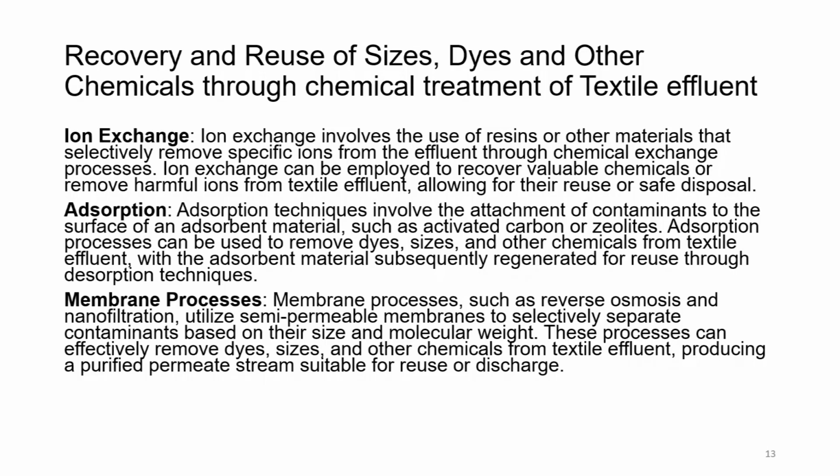So, just a while ago we understood that adsorption is for removal, desorption is for recovery, and if that can be done effectively, there is a lot of cost saving and there is automatically a lowering of pollution load.